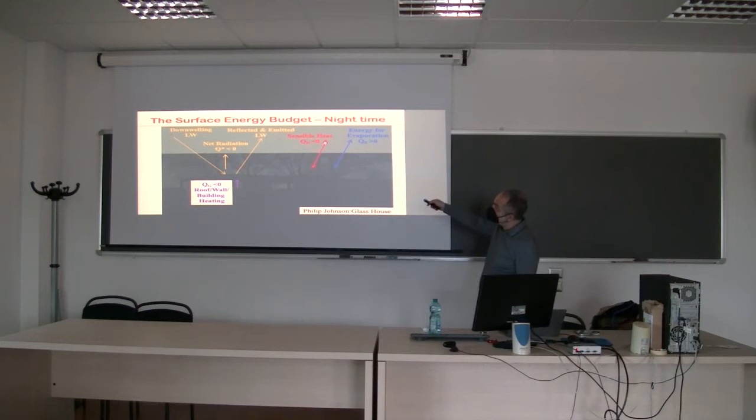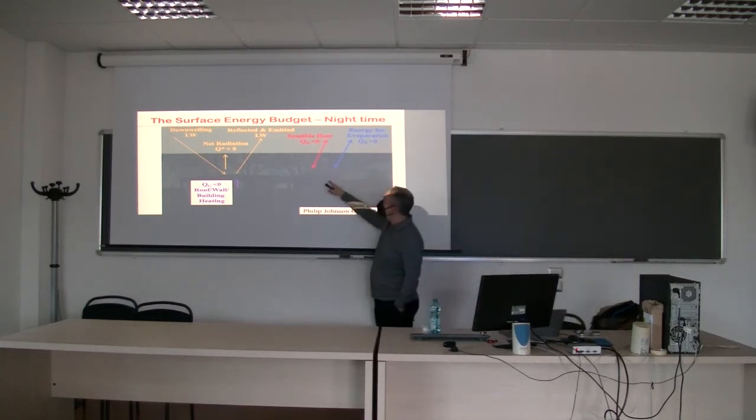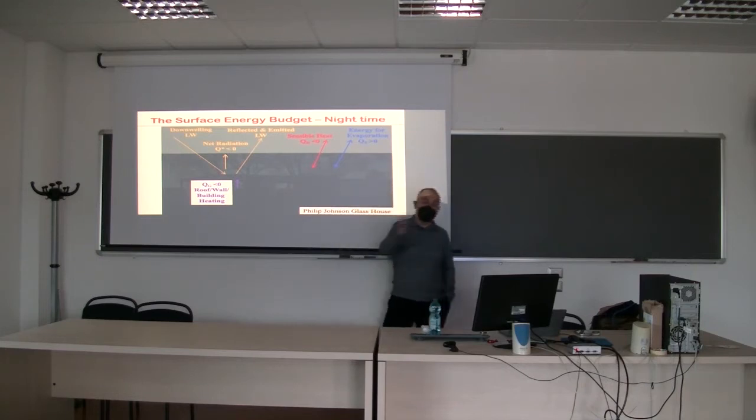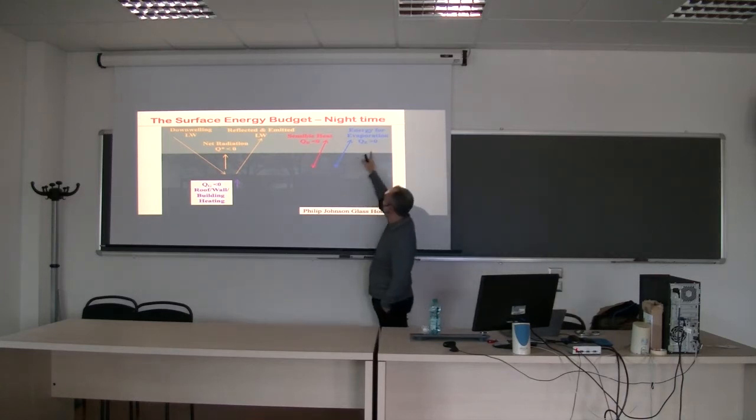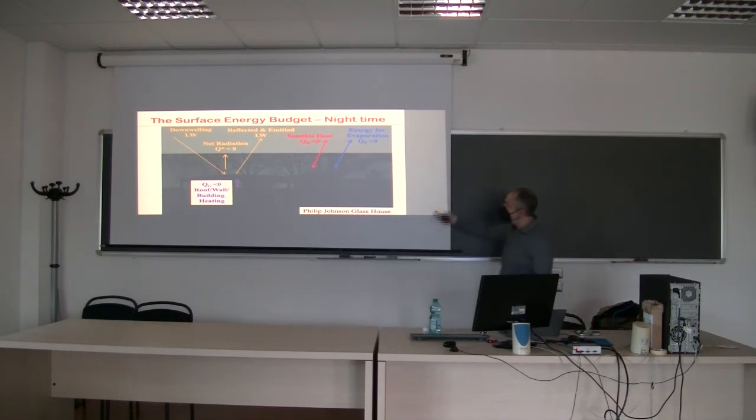But that's not always the case. It could be the other way around, but typically the heat is going to go from the air to the surface. And evaporation, if the roof is still wet, it might still evaporate, so you get a positive QE upwards. And if you have dew formation, it's the opposite. Dew formation, meaning there's condensation onto the surface and basically negative evaporation. So this one could be actually negative, but most of the time this is going to be zero or positive, and these are going to be the main sources of energy going into the interface.